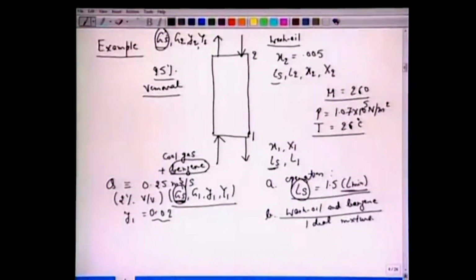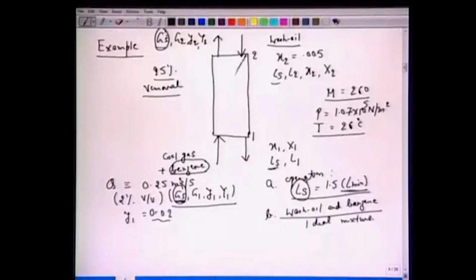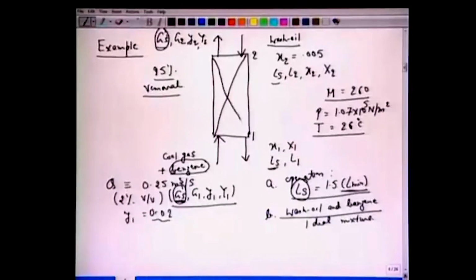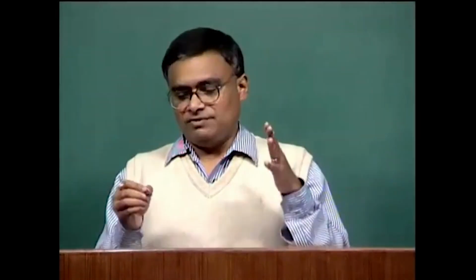Okay, so before we proceed further, it's a good idea to graphically understand what we want to do here. The most standard procedure, it's recommended that we follow, is to draw a schematic of this absorption column. It's a packed bed, so we draw it schematically like this. It signifies that there's some type of packing. We mark the streams, inlet and outlet, and put the specs there: x1, x2, y1, y2 at both locations 1 and 2.